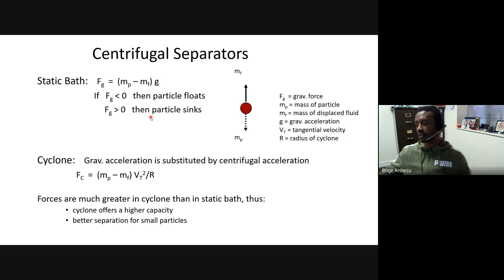As I told you, that's just the principle we're using. But in some cases, especially for fine particles, that may not be enough. Why? Because although fine particles are denser, if the media is of reasonable density and the particles are really fine, they may not actually have the ability to sink through that media. So they may not be separated out properly.